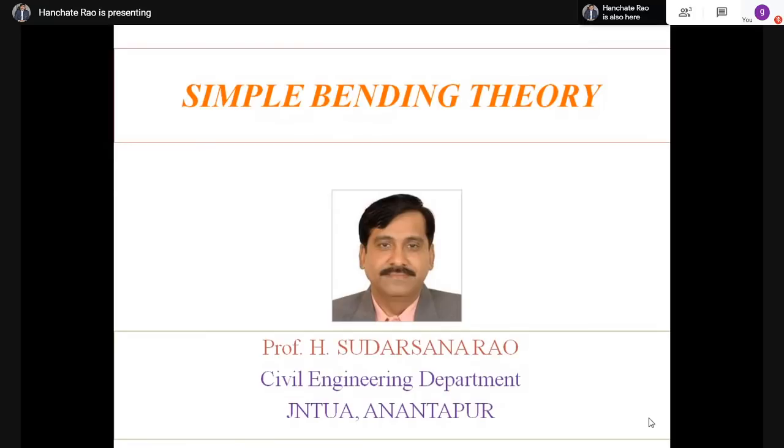Dunnavamshikrishna@gmail.com is asking: right hand side upward shear force is positive, then you told right hand side negative. So Vamshi Krishna, I am once again clarifying that the sign convention can be followed as per one's choice. Right upwards negative, which I have proposed, is an internationally accepted sign convention.